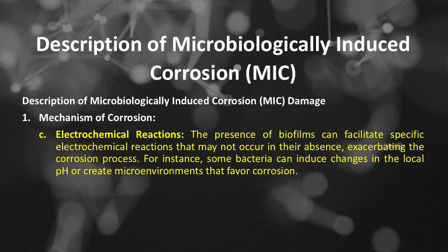Number C, of mechanism of corrosion is electrochemical reactions. The presence of biofilms can facilitate specific electrochemical reactions that may not occur in their absence, exacerbating the corrosion process. For instance, some bacteria can induce changes in the local pH or create microenvironments that favor corrosion.